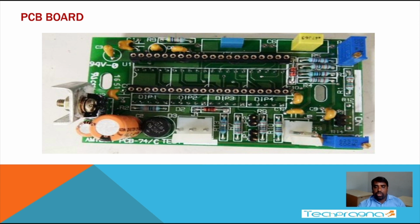So what are all the components we have? We have two types of components: SMD components and through-hole components. What is the difference between SMD and through-hole? SMD is a surface mount device. We place the components on the board and the soldering is done right there on the same side. If I am taking through-hole components, I place the components on the board and solder on the bottom side of the board. So that is the difference between through-hole components and SMD components.